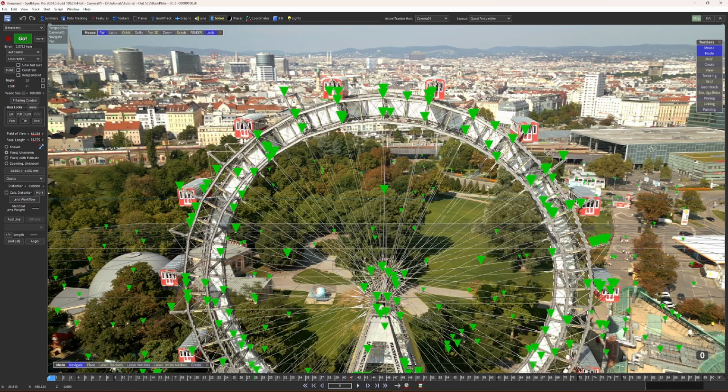That means the camera has some distortion, and we can integrate the lens workflow to decrease the error level again. But in our example, I don't want to integrate the lens workflow because, from my point of view, it's tracked with a level of 0.57. It's okay. But anyway, we will optimize our 3D camera track.